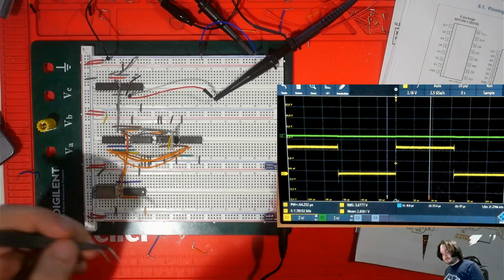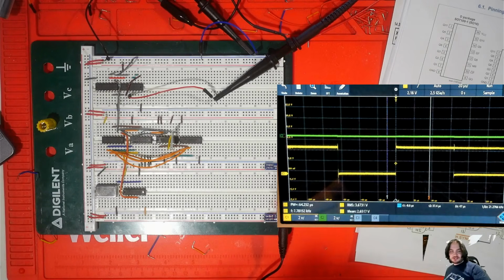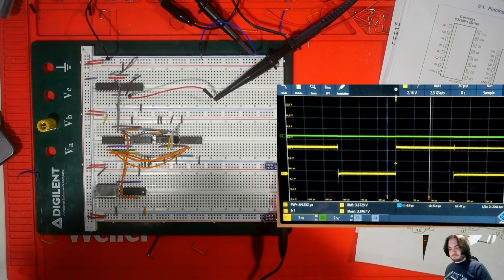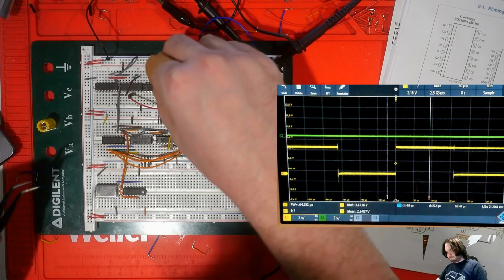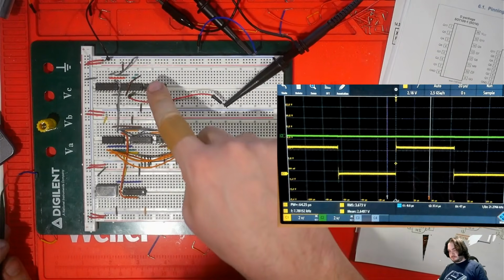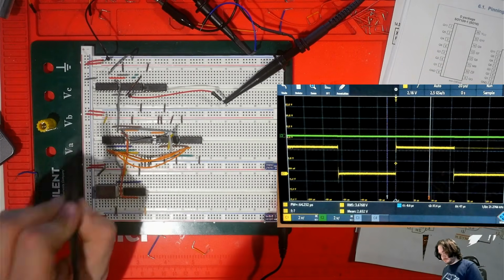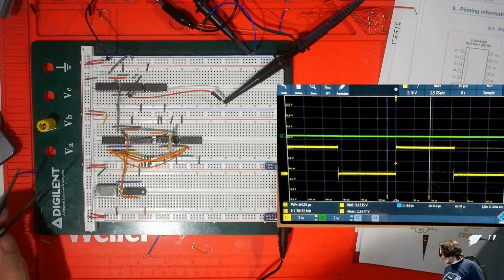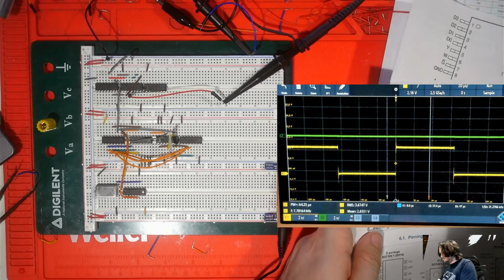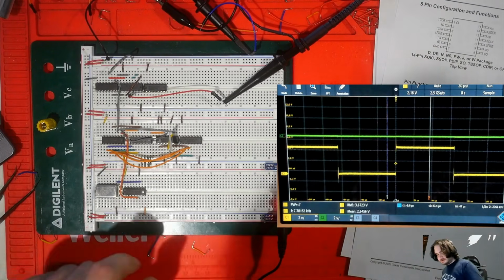So we're getting some signal out. Ultimately, our goal is to capture that with another 74HC74. So let me just grab that one out. Next we capture, same as before, we want to capture that on the clock.